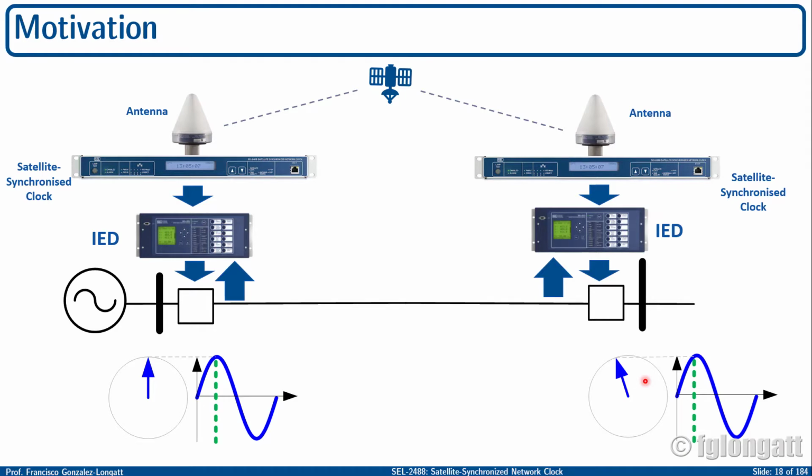And the modern electronic devices that we are using for protection today at various substations are doing the phasor measurement and creating those phasor representations. Again, what you need to understand here is that we need this very precise and synchronized satellite clock in order to create the reference for our phasor system.